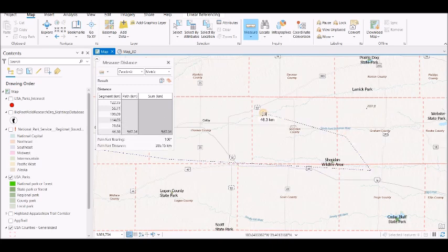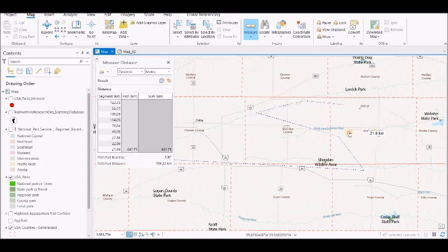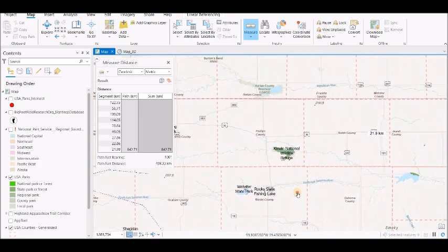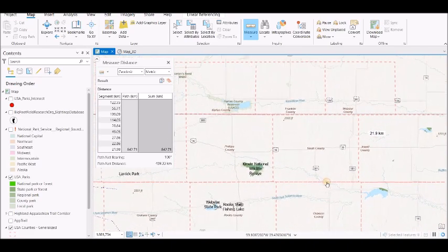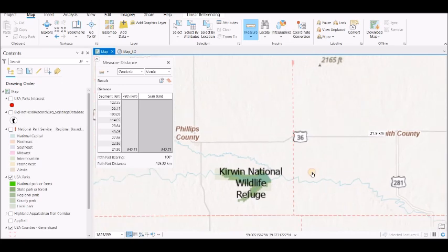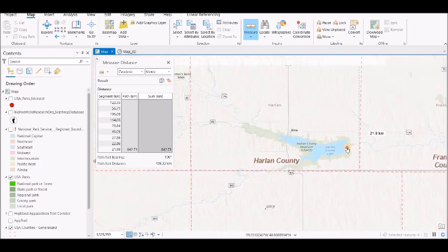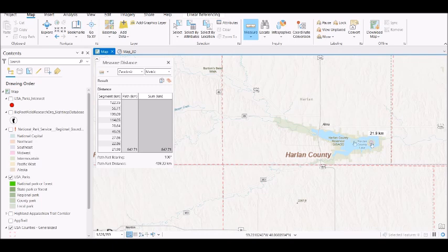Anytime that you've got another tool active, all you have to do is push C on the keyboard, and that activates the zoom control tools. You can use your mouse to scroll, pan, and move the map around, so to navigate the map, basically. And when you let the C go, whatever tool you had on will be activated.